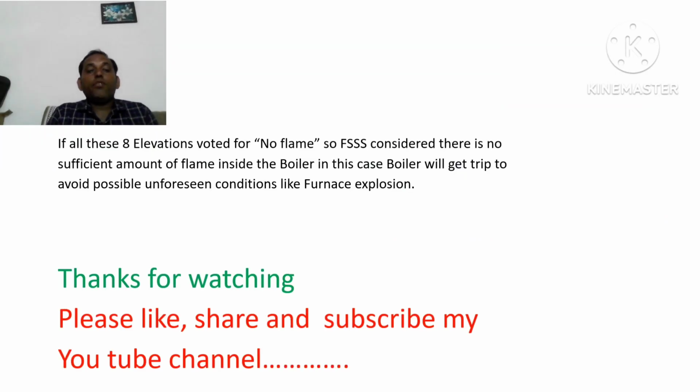If all these 8 elevations voted for no flame, FSSS considers there is no sufficient amount of flame inside the boiler. In this case, the boiler will get tripped to avoid possible unforeseen conditions like furnace explosion.